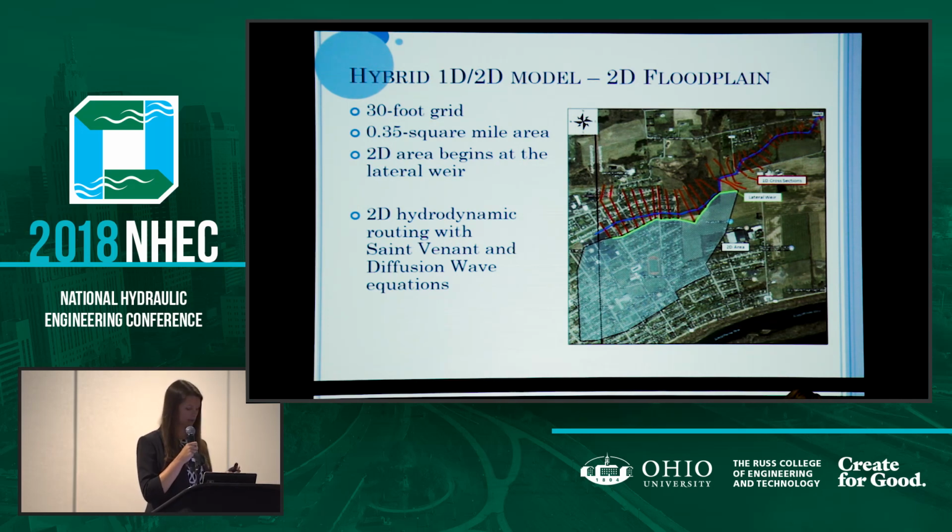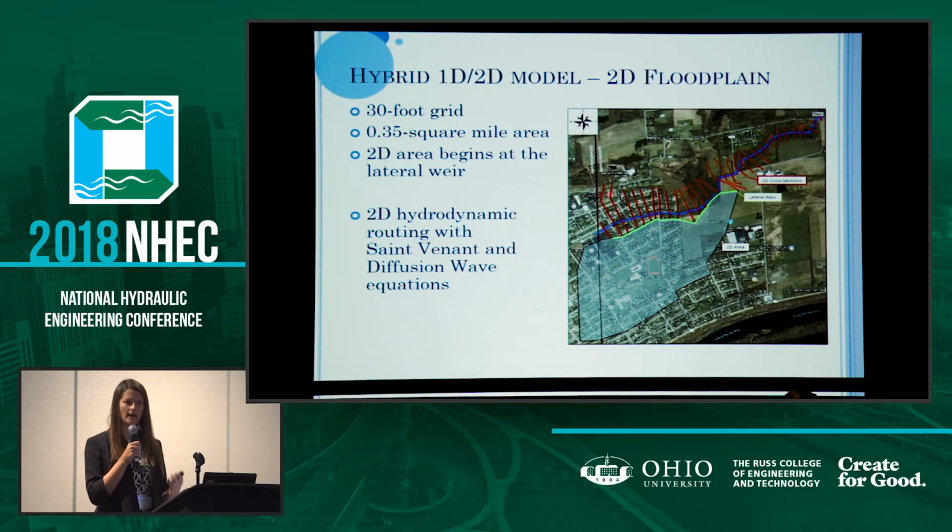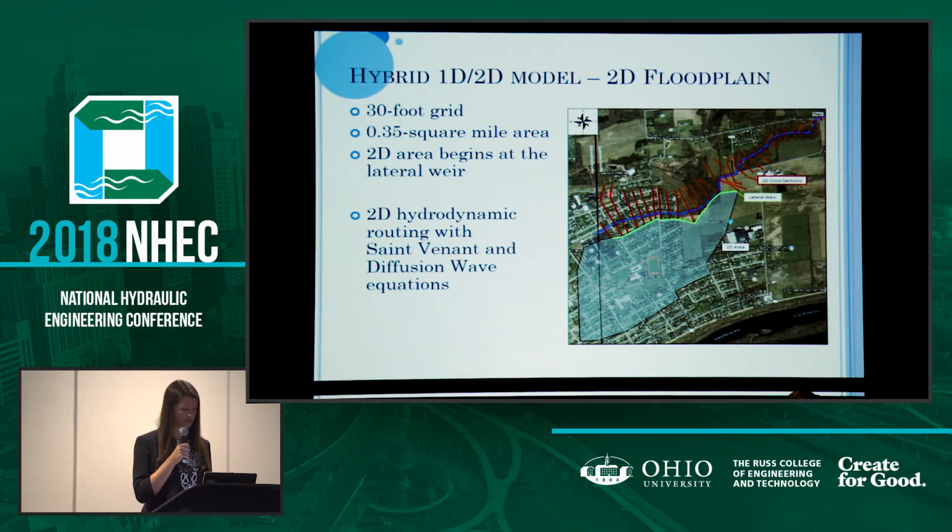This was a critical component of our HEC-RAS model since the lateral weir calculated how much flow would remain in the system and how much flow would leave the system and head into the southern floodplain. For the weir coefficient, we performed a sensitivity analysis in HEC-RAS, and we also compared it with another 2D model, TUFLOW, in SMS.